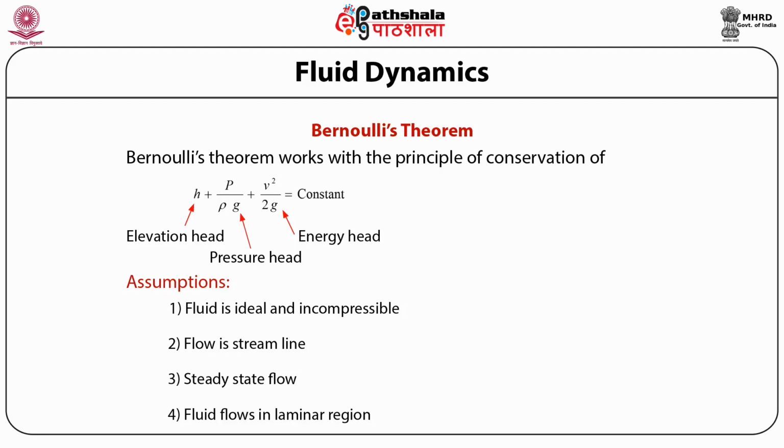If we consider a column of fluid of height h, the total force applied will be rho A g h. The pressure, F by A, can be represented in terms of the head, small h, which is equal to P by rho g. Kinetic energy is always associated with the movement of fluid mass, so the kinetic energy can be best described by the velocity of the fluid.